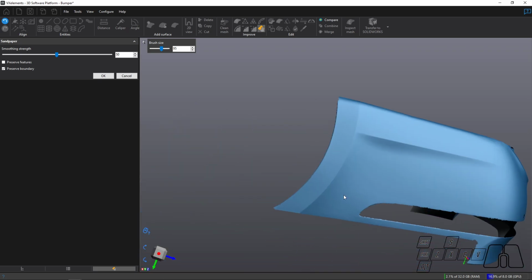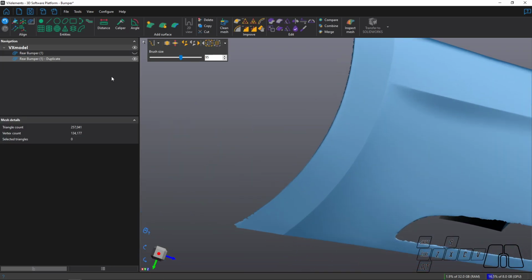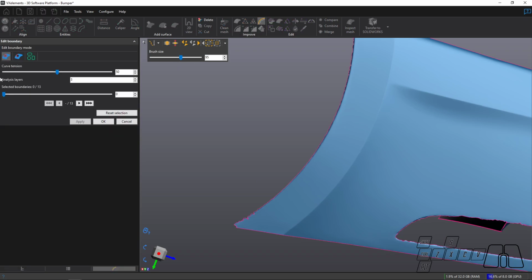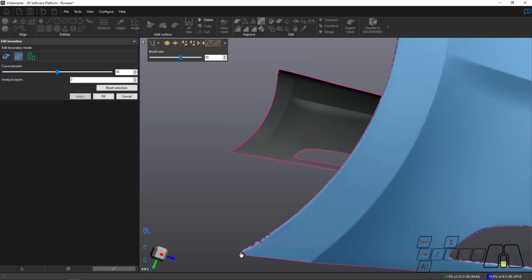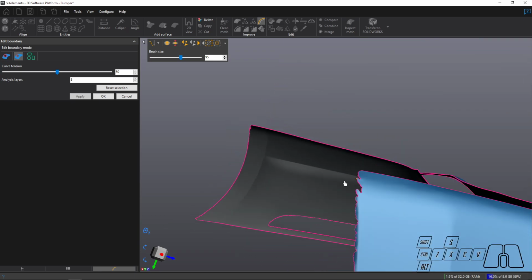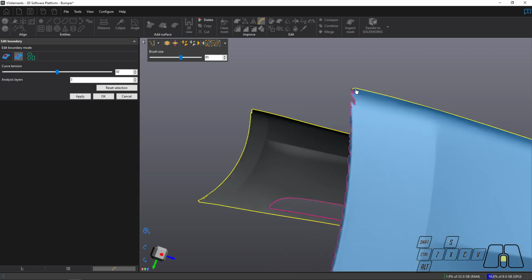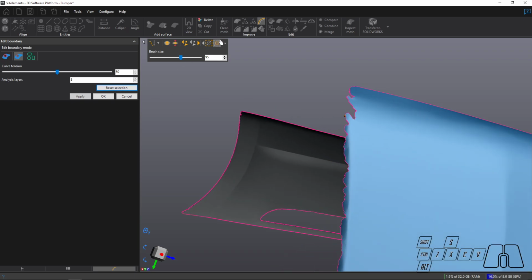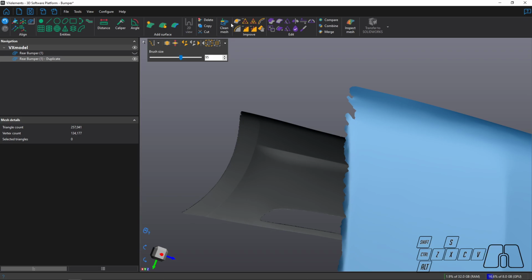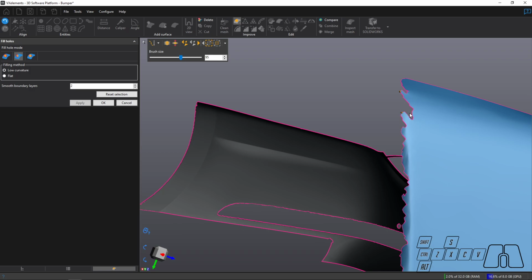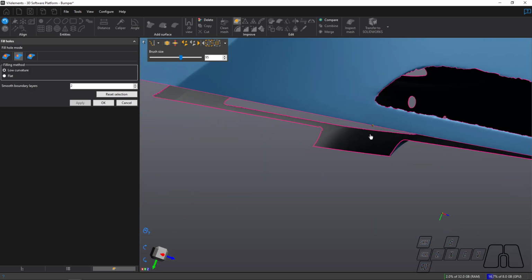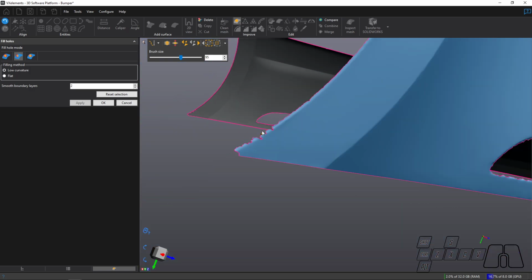Right on. So now that we have smoothed out our mesh or removed the features that we had, then we can proceed and start cleaning up our boundaries, which is what will take us most time throughout the entire cleanup process. So in some cases, it's a good idea to, while we are doing this, fill partial holes. For example, this one over here.